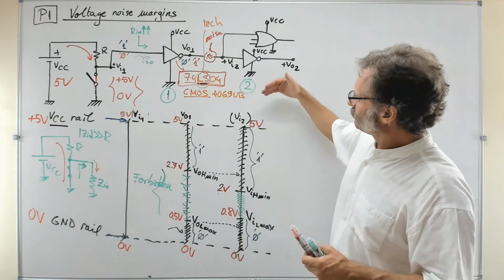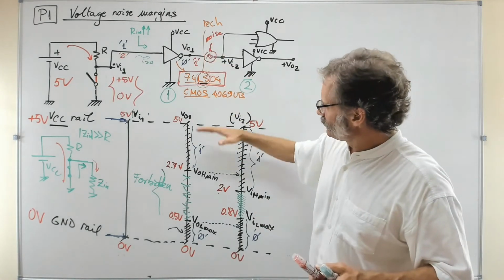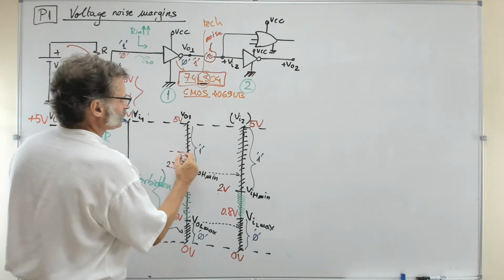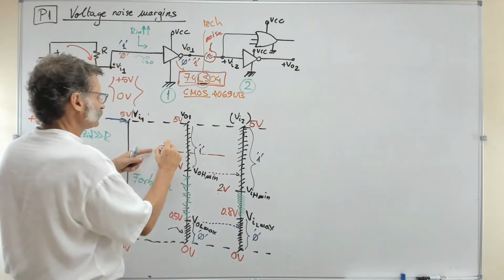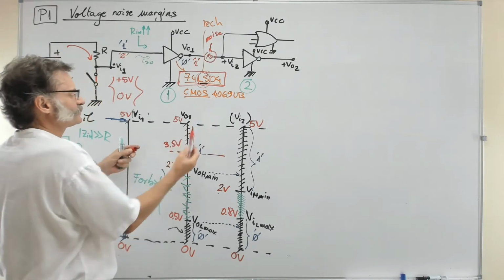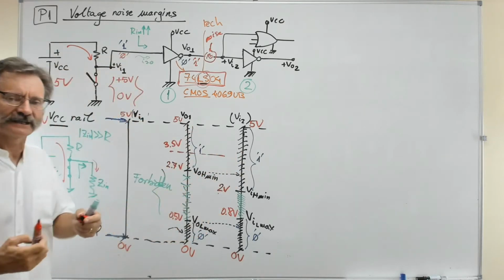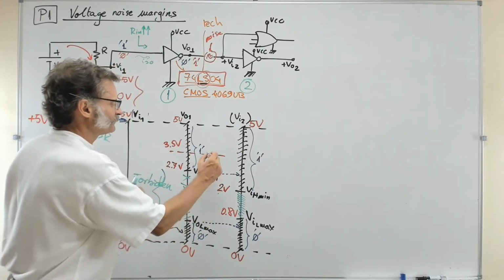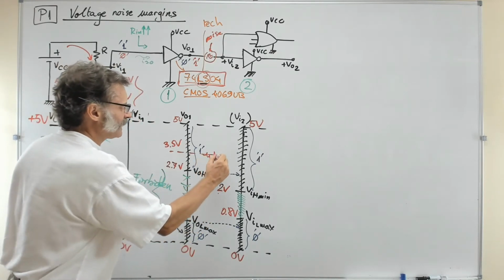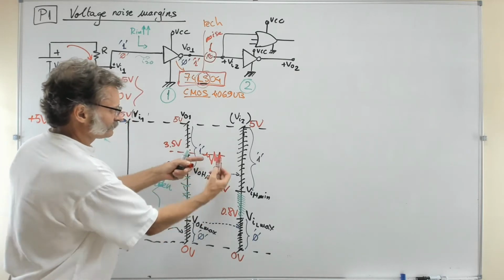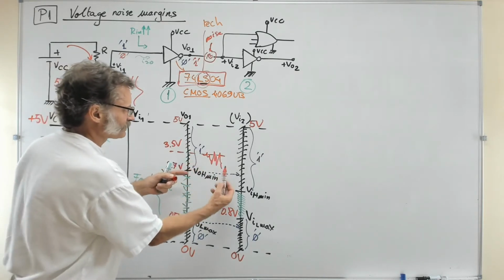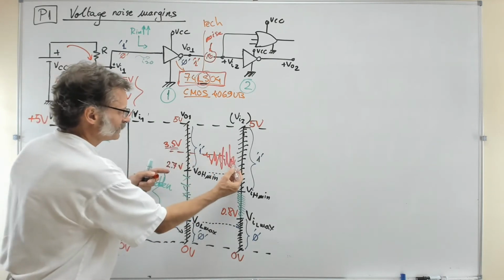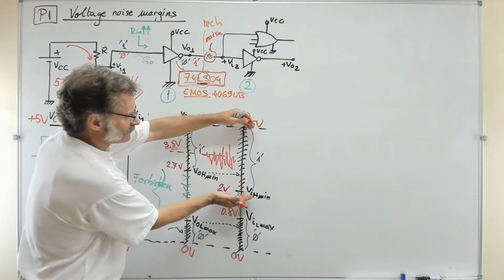So the wire, for example, may be clearly generating a 1. Let's imagine that the typical value is 3.5 volts. So the gate is generating 3.5 volts, and then it is attacked, or it is picking up some noise. What is the meaning of this? Well, if the noise is not that high, nothing happens here, because even if the voltage varies around the 3.5, it is covered in the margin that is understood as a 1.